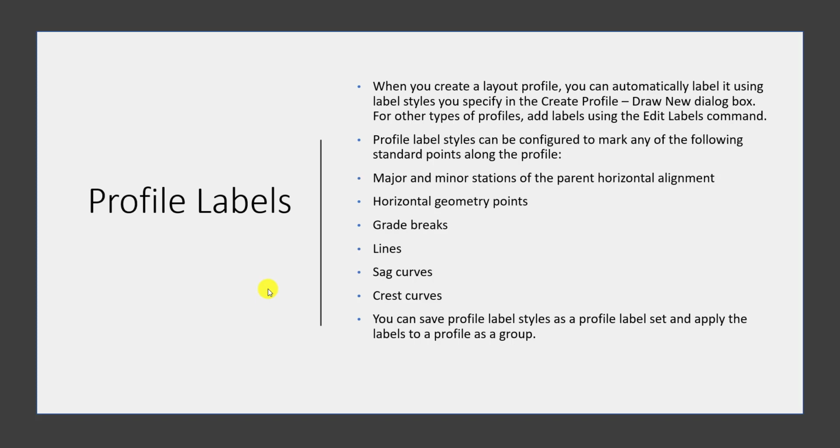So profile labels, when you create a layout profile, you can automatically label it using the label styles you specify in the create profile, draw a new dialog box. For other types of profiles, you can add labels using the edit labels command.